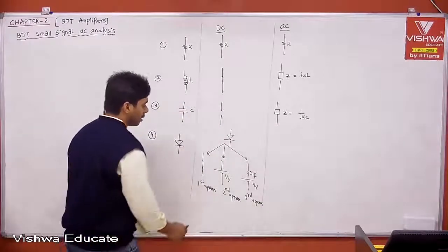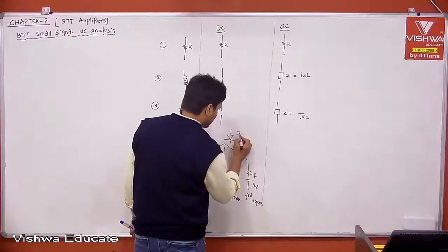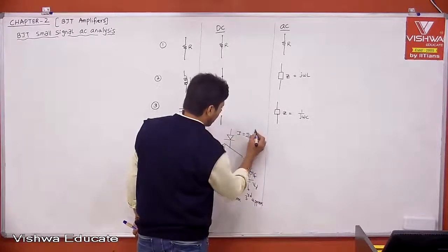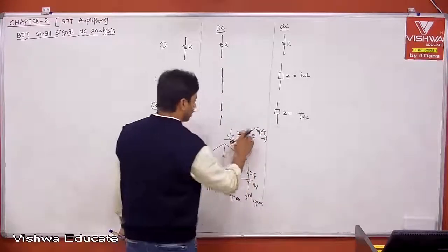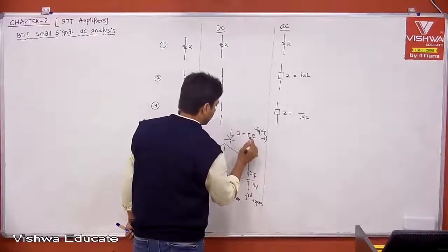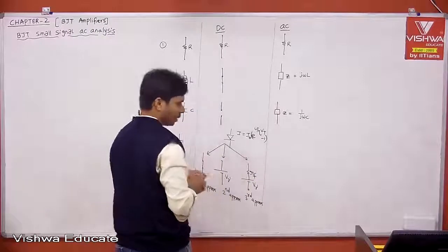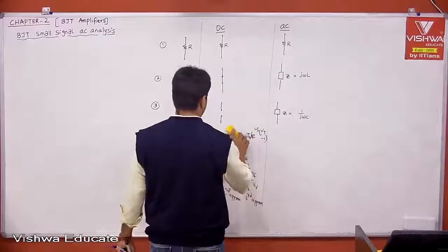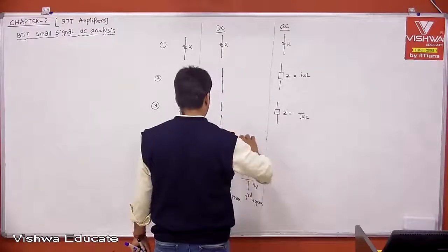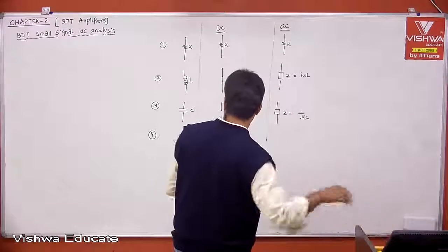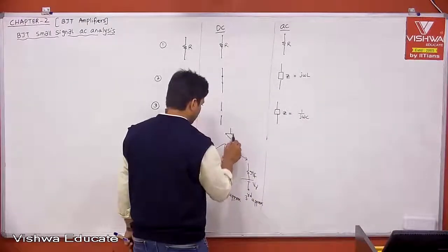What is the exact model? Therefore the exact model equation is nothing but, this is supported by I is equal to I naught into e to the power of V by eta Vt minus 1. This is your PN junction diode.